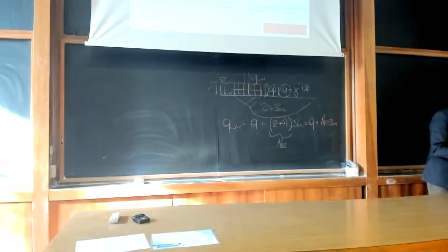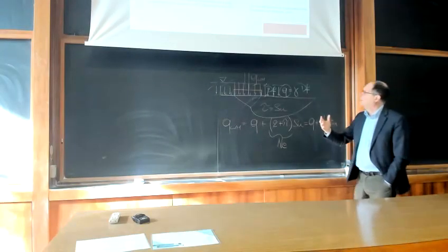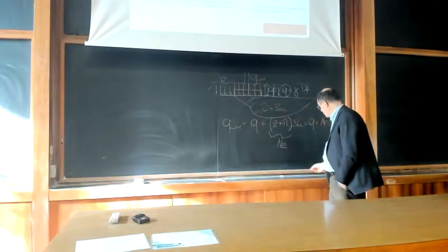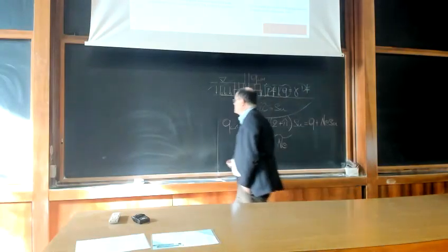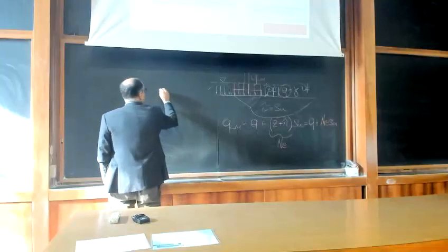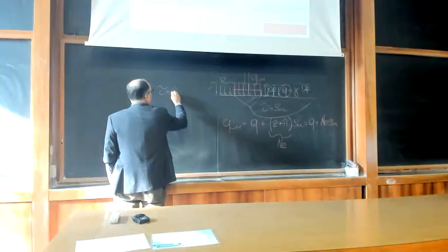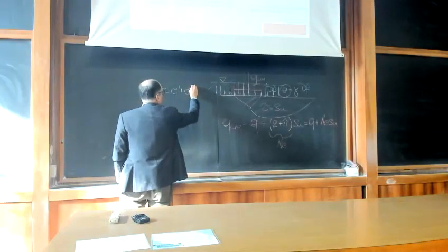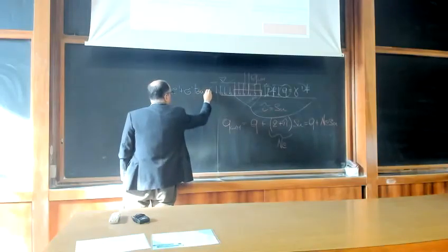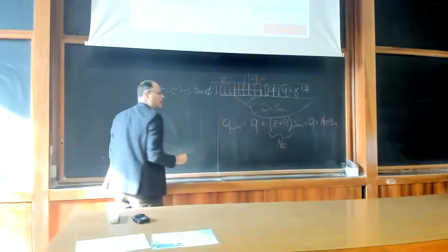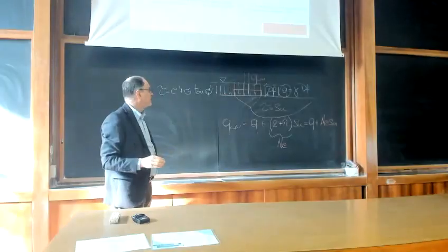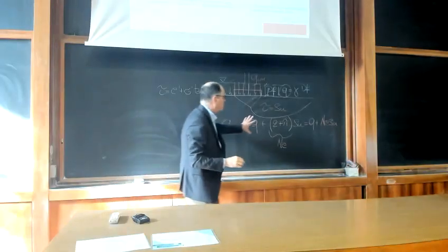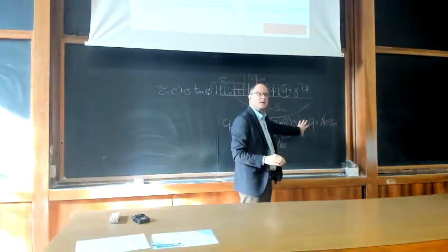So this is the typical situation of drained conditions. In that case, you can no longer express the shear strength of the soil by the Tresca criterion, but you have to use the Mohr-Coulomb criterion in effective stress terms.